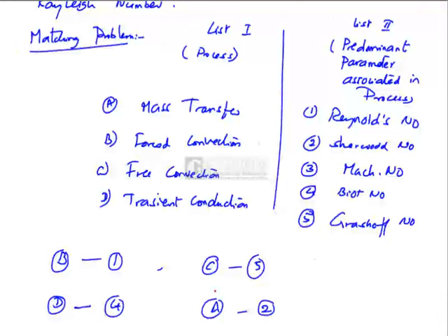In fact, Mach number would appear only in compressible fluid dynamics, or when the velocities of the fluid are very high, in the range of velocity of sound. Particularly when the compressibility effects of the fluid are taken into account, or when high density changes and high pressure changes are involved, where shock waves are formed, Mach number plays a predominant role.